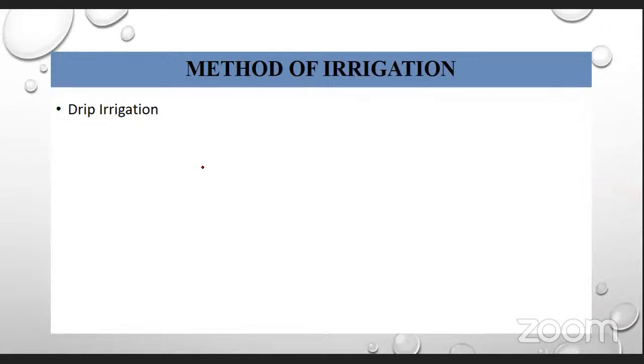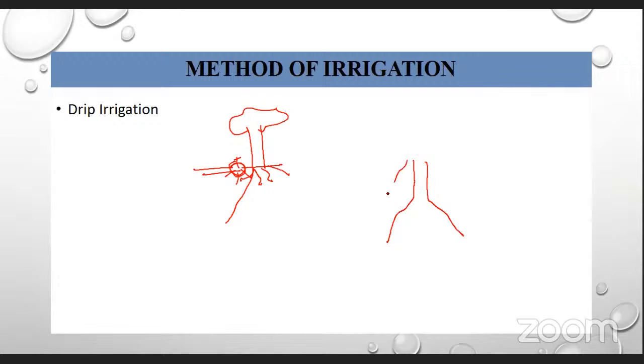As you see, in drip irrigation we are applying water to any tree through the emitters. So the roots will not be very deep, because roots usually grow deeper in search of water only. If these roots get the water only through the shallow soil surface, they will not grow deep.